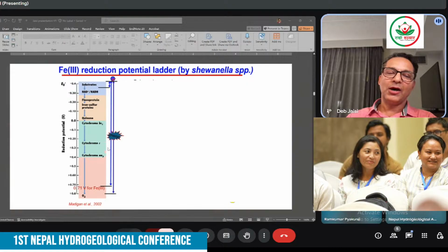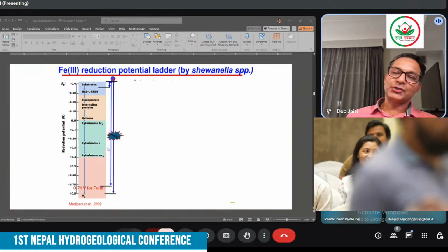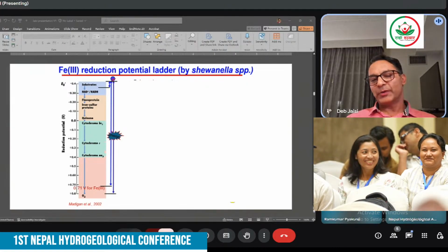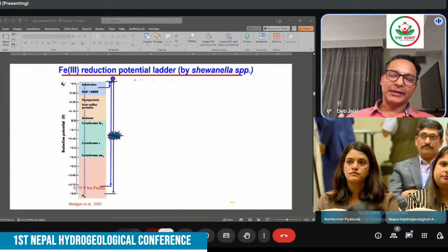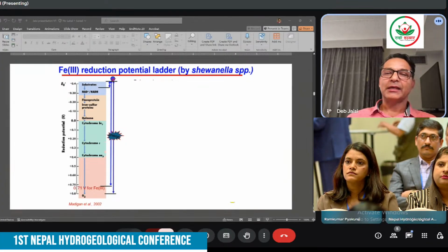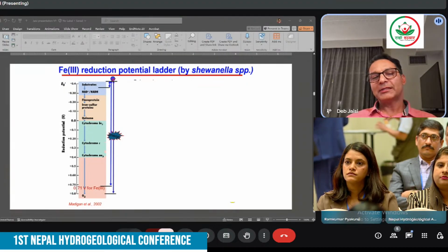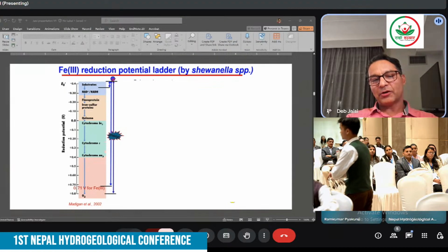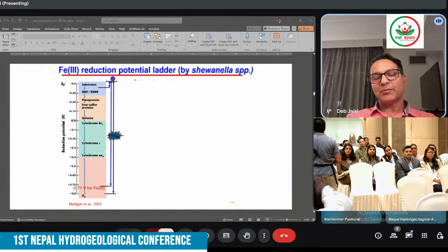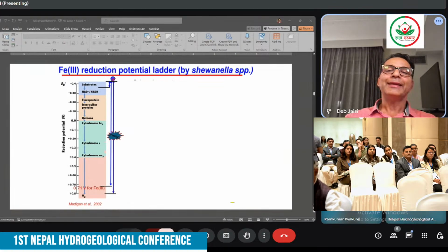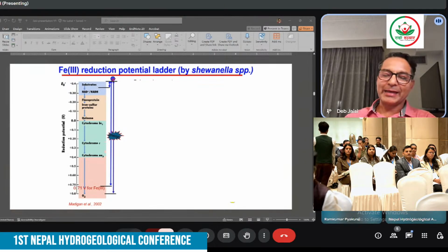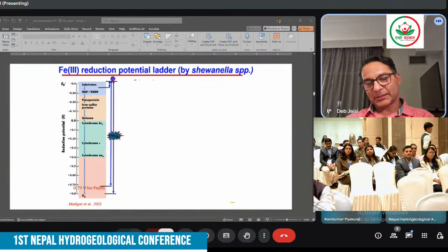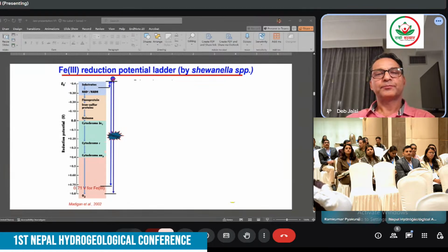In the anoxic zone, the phosphate oxygen is completely equilibrated with water oxygen. That only happens if there is significant biological cycling in the aquifer. It means a certain part of the aquifer has a whole lot of microbial processes happening, changing the isotope composition of phosphate as well. So this is one way of confirming biological cycling in the aquifer.